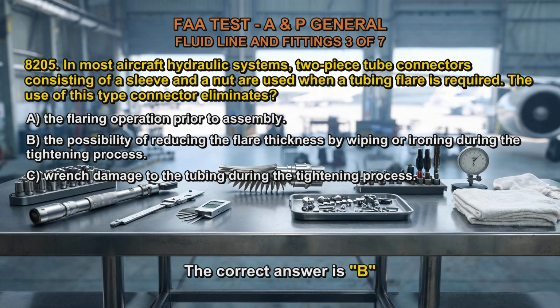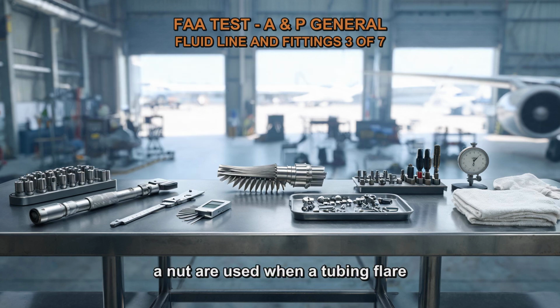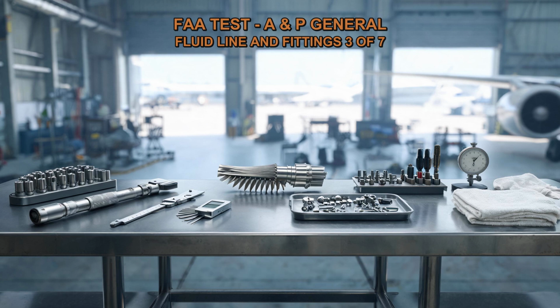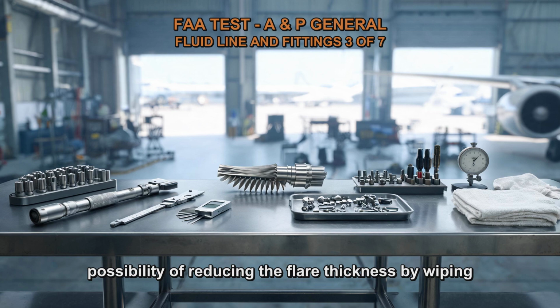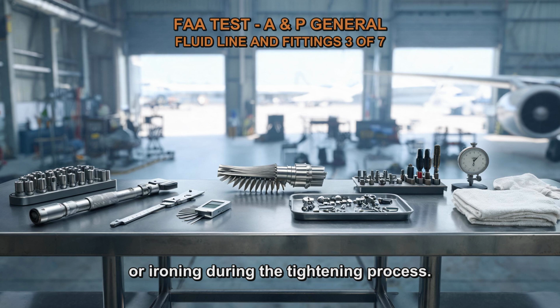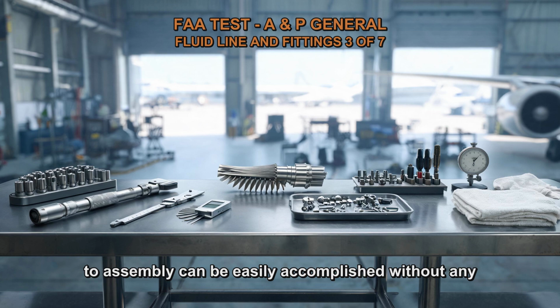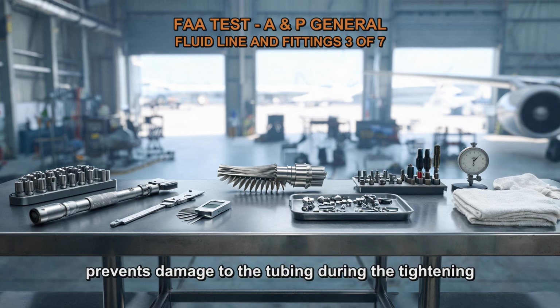The correct answer is B. Two-piece tube connectors consisting of a sleeve and a nut are used when a tubing flare is required in most aircraft hydraulic systems. These connectors are specially designed to eliminate the possibility of reducing the flare thickness by wiping or ironing during the tightening process. By using these connectors, the flaring operation prior to assembly can be easily accomplished without any damage to the tubing. Also, the connectors have a wrench flat that prevents damage to the tubing during the tightening process.